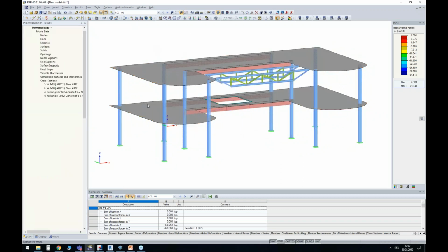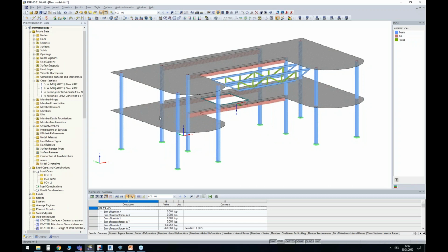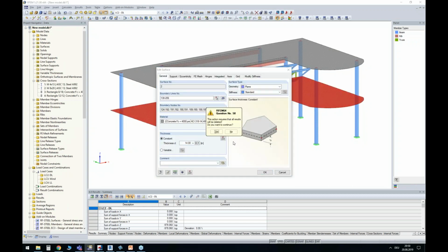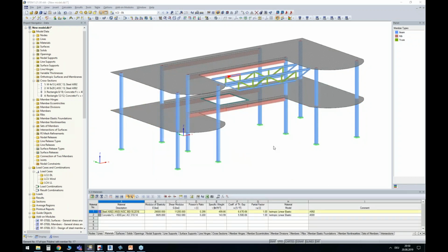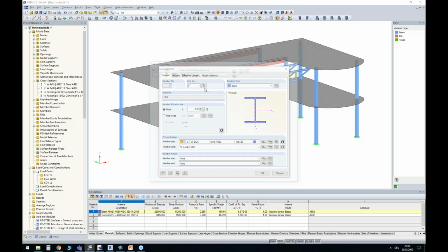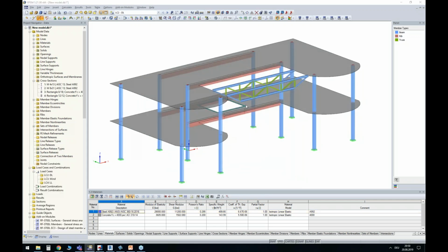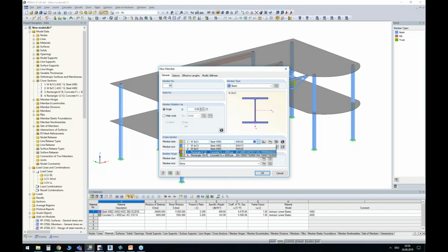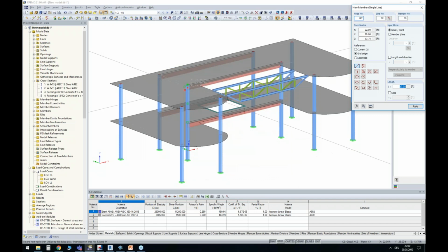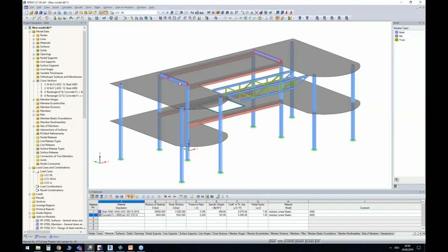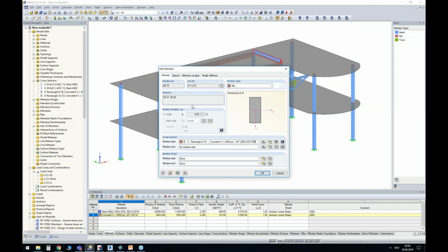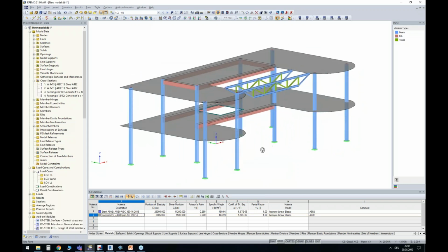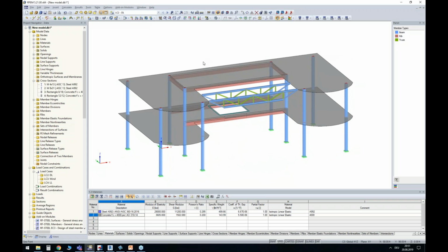We do the same again as what we did before. We will change the thickness and the cross sections and so on. So we skip the design again. I will change the thickness of that surface again to 14 inches. I will change the cross section of the upper girder again to W8/31. And I will also create these additional members here. I will assign the same settings regarding the ribs. They should be placed on the plus Z side, equally to the other downstand beams. And yes, that should be all.